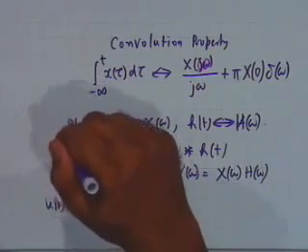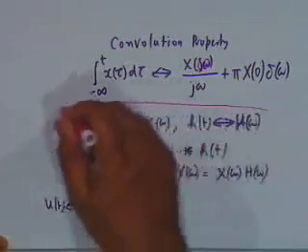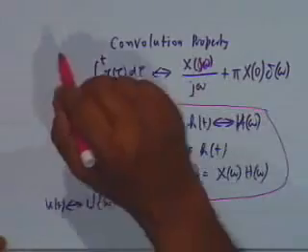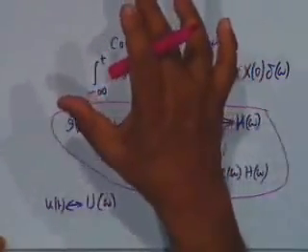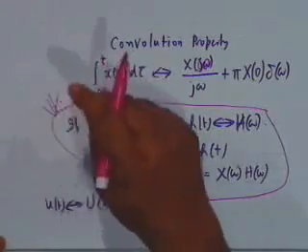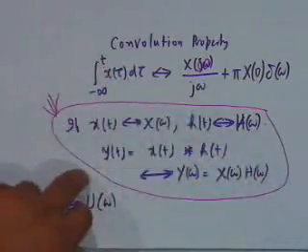In the conventional sense it doesn't exist, but we decomposed it into even and odd parts, and then proved that the Fourier transform of this contains a delta function in the frequency domain, and that's how we arrived at this. As I said, the convolution property was proved in a casual manner, as if the main importance is to prove the Fourier transform of integration. This by itself is an extremely interesting property, that convolution in the time domain becomes multiplication in the frequency domain.